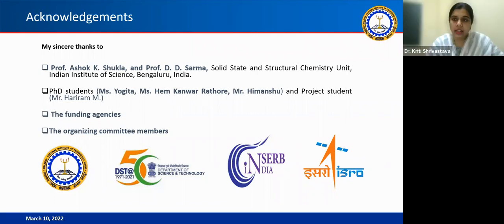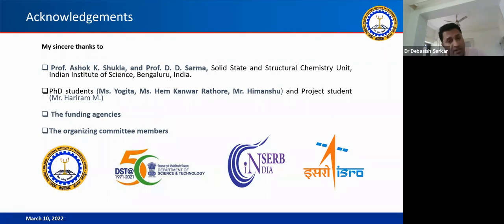So, sir, in that case, can we prepare a symmetric or asymmetric type of supercapacitor, if we are using only the carbon material? Okay, you can try it both ways. You can go for making a symmetric one, but the potential window will be limited in that case. So if you need to increase the potential window, you should definitely try for an asymmetric one.